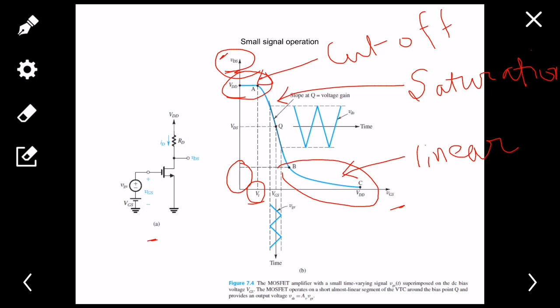And if I put an input signal, a small AC signal like this at the gate, this is a small AC signal. If I apply this one, see that this is the VGS, the input, right? Gate to source. Now let's forget about the DC supply, because the DC supply is here to give you a bias voltage, and I want it to be in the saturation region.